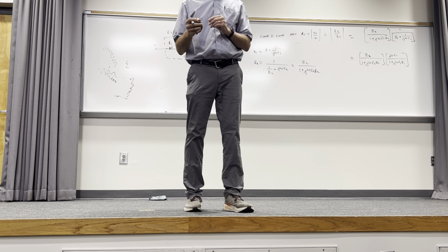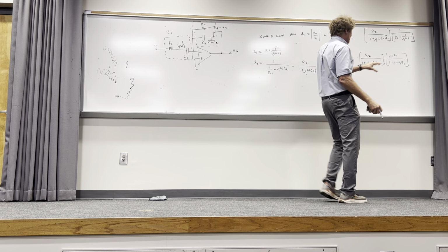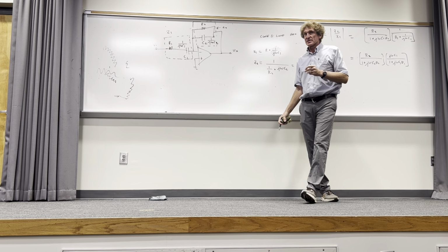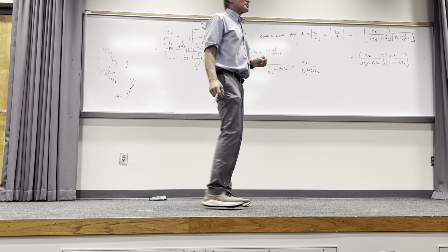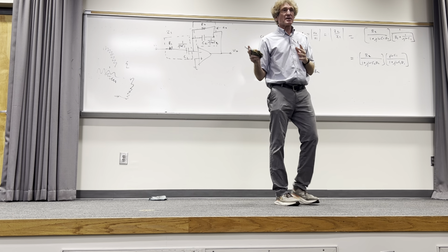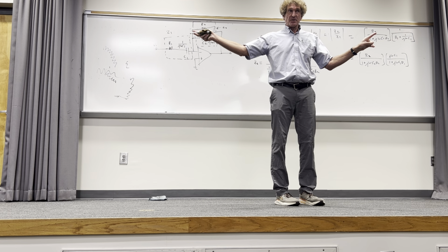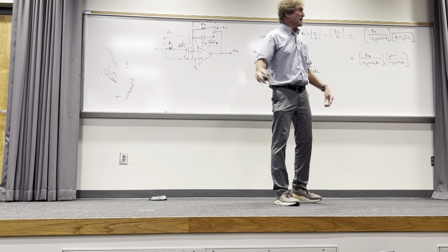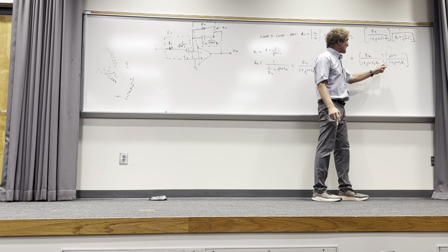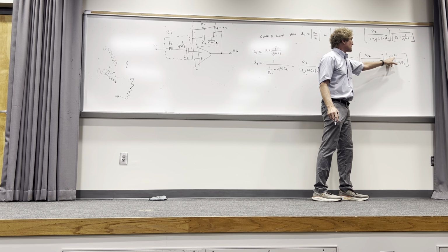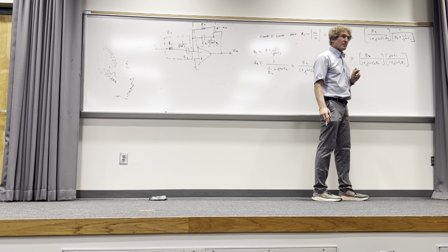Now when you see that, first of all, it doesn't look like the other ones because of this stuff. So here's how you evaluate these things, the type of filter. Listen, first you let omega be 0. You do this at the extremes. We're going to look at omega equals 0 and omega equals infinity. You all follow me, class? So at omega equals 0, if you put a 0 down here, it's 1. A 0 here is 1. A 0 here is 0 times anything is 0. It is 0. Do you all follow me?